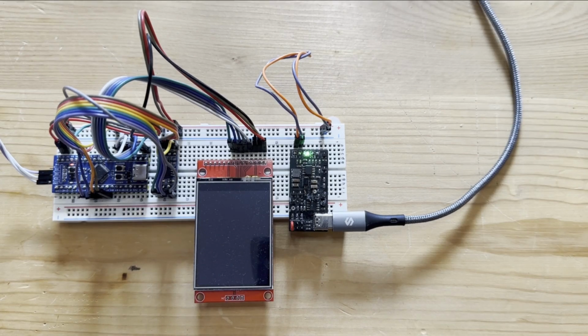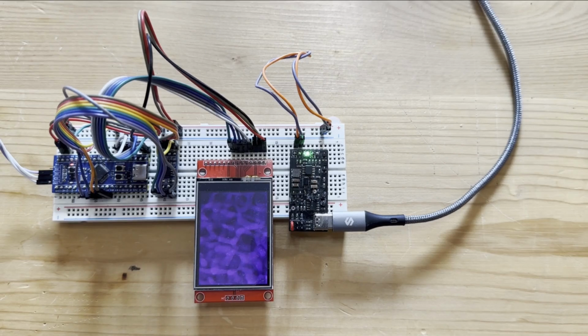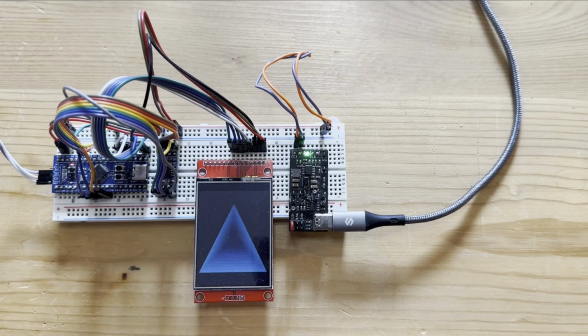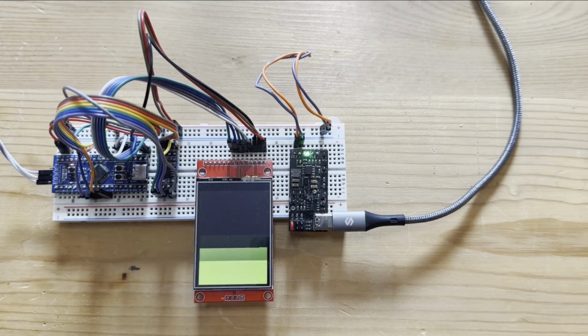Yes, or almost yes. In this video we will see that, setting up a proper driver and having previously created an external loader for the SPI Flash in our project, we can easily handle data stored on it, moving data from the internal to the external flash in case of a new memory allocation or a new configuration, and accessing data stored on the internal and on the SPI Flash in the same way.